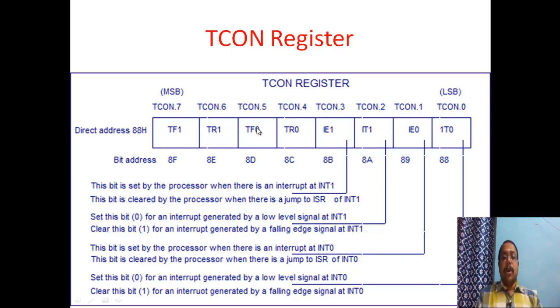So what you will do is set this bit and wait for the flag to be set. I repeat, whenever you set the bit TR0 or TR1, the timer will start. Then you only have to monitor the bit TF0 or TF1. Once this is set, we come to the conclusion that the timer work is completed.